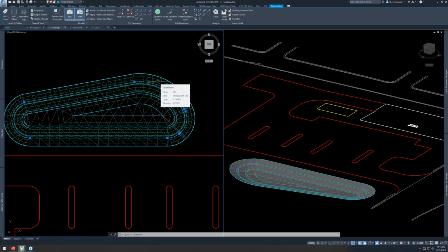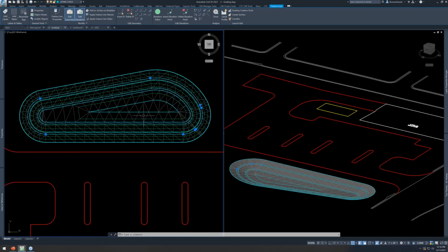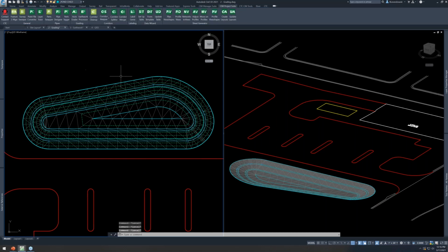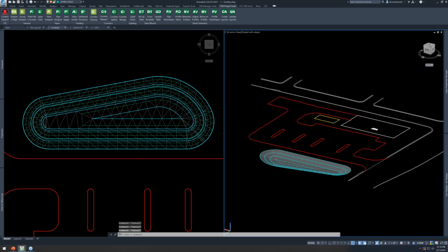Okay, so AutoGrader will apply the exact rules you specify in there, including overwriting vertices that you may have manually added. So there may be a point where you're done with AutoGrader and there's a couple little tweaks you want to do, but you'll be surprised how much AutoGrader can cover. So let's move on to some parking lot grading.